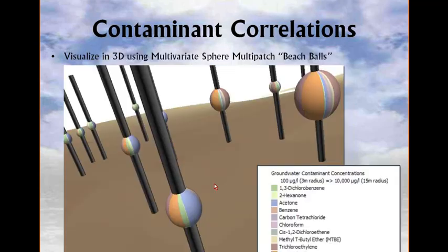To do with our cross-facility new feature, we'll actually do that later. We'll do pie charts for, say, metals, and we can look at signatures throughout all your facilities. It's helpful also for background identification. The 3D version of the pie chart, we call them beach balls, and so the added dimension you get here is the Z direction. So you not only can do aerial fingerprinting, but by depth. So you can sometimes see different signatures as you go deep. This could be done with soil data too, not just groundwater data.